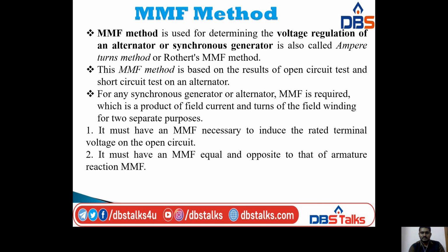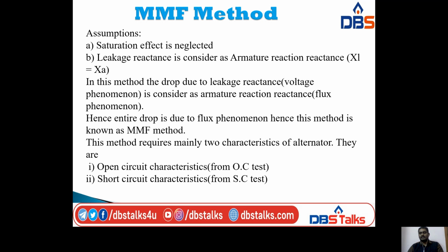These are the two separate purposes for which we use the MMF. As in the previous method, we take some assumptions: the saturation effect is neglected, and leakage reactance is considered as armature reaction reactance. So the drop due to leakage reactance is considered as armature reaction reactance, as I discussed in the EMF method also.